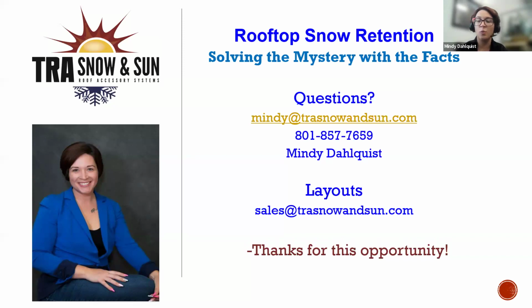We engineer to worst case scenario, and we surpassed worst case scenario last year in Utah. We had higher storms than we had ever seen. Luckily, we didn't see any issues or concerns from that, but it is very, very important that you're not taking away from the structure to cut corners or save money, that you're utilizing those heavier snow loads and utilizing ground snow loads when you're using any kind of snow retention device on the roof.